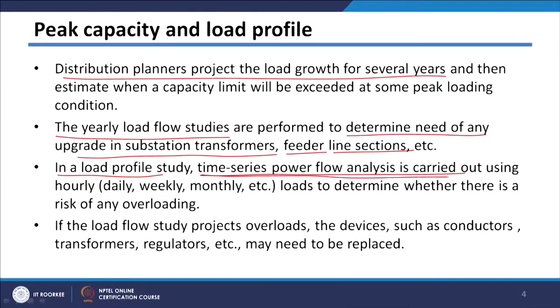So if you are considering a year, you can calculate at each of the months. If you are considering a day, it can be calculated at each of the hours, or even at each 15 minutes. So in this case, this time series load flow analysis will be carried out using hourly, daily, weekly or monthly, depending upon how much time period you are considering, to determine whether there is a risk of any overloading. So you have to find out if any component is getting sustained overloads.